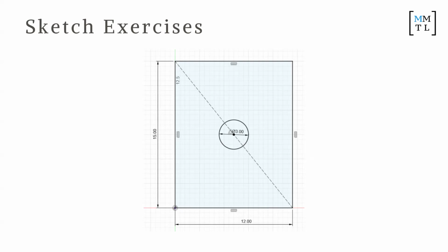What you're going to notice is it might be difficult to snap your circle into the center. So you can just draw a circle anywhere first, on the side, with any dimension. You don't need to enter anything, just click. Nice. Has everyone made a circle next to the thing?